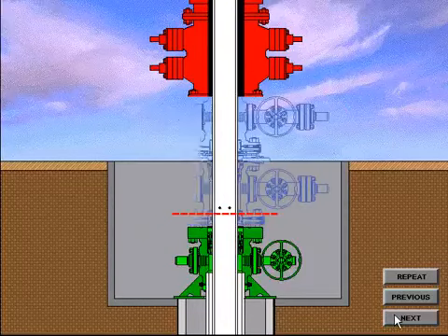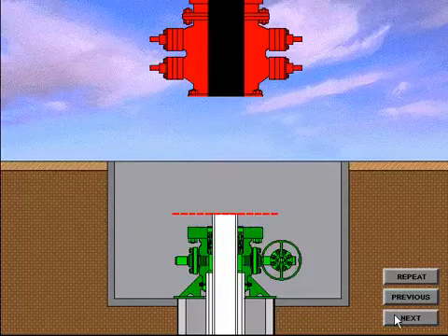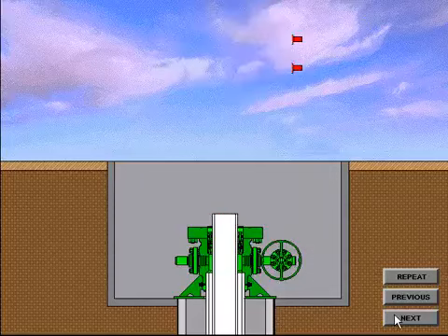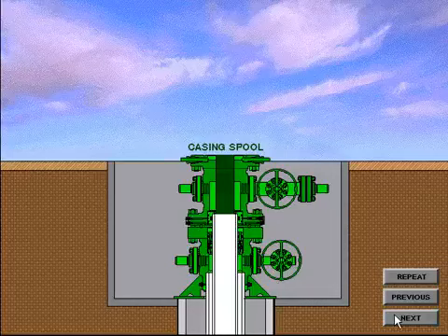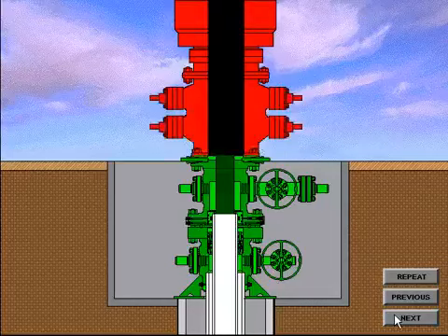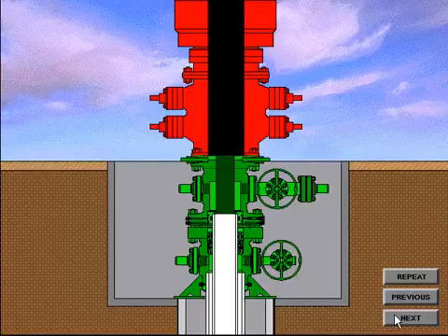When the casing is drained, a rough cut is made and the balance of the casing riser is removed. The BOP system is removed. The casing spool with a crossover seal is installed. The BOP system is nippled up and preparation is made to drill out for the production casing string.